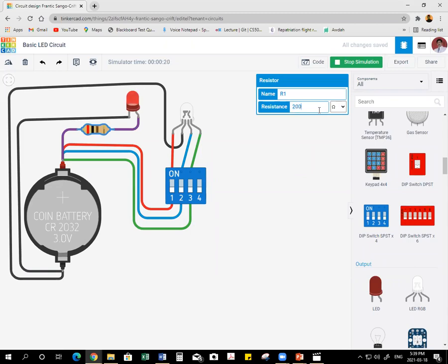Now see that. Now I will change the resistance value to 20. Now the problem is here, it is showing 28 milliamps. Means we can have a slight increase from 20. So we'll have 30. No, we must have 40. Okay. So let's try 35. No. So we need 40 ohms. Okay, there won't be any problem. So this is brighter compared to the previous one, this LED is more bright. Now this is the basic one.